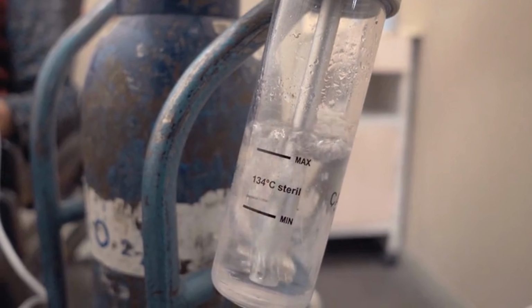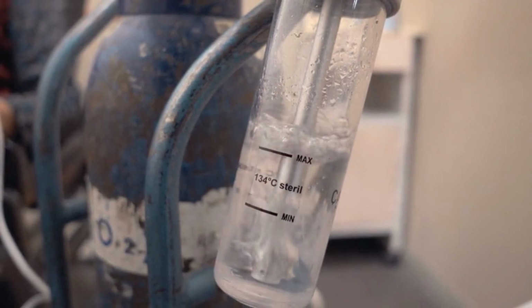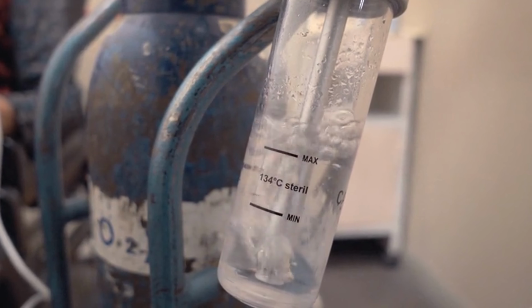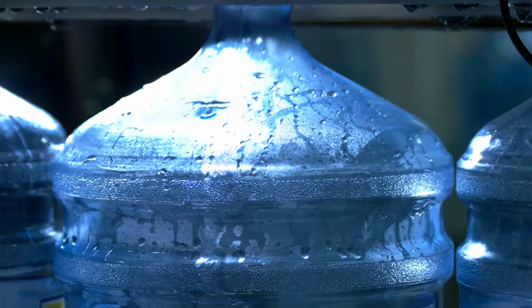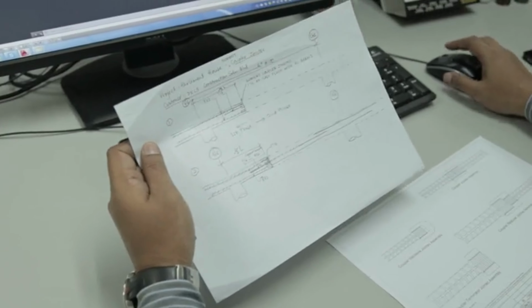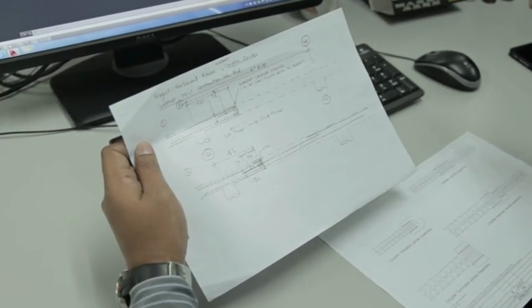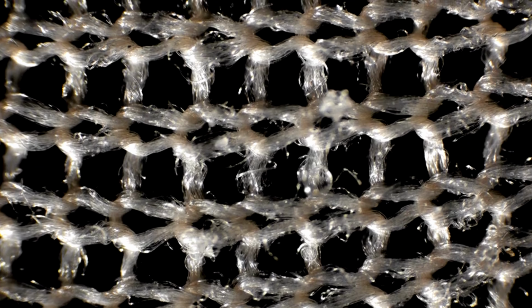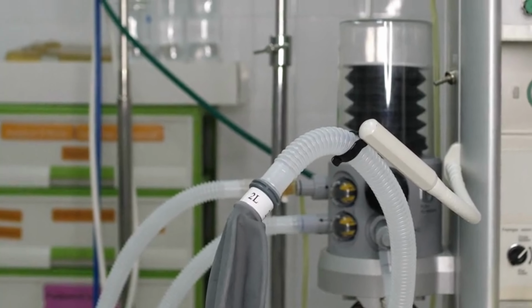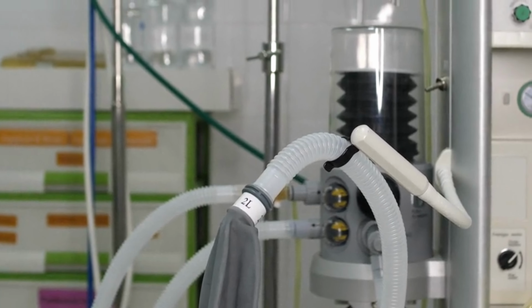5. Paper formation. After pulping and refining, the pulp is diluted with water, typically 99% water and 1% fiber, and pumped onto the fourdrinier or cylinder machine to form the paper sheet. Key steps. Wire section, sheet formation. The diluted pulp is spread onto a moving wire, a mesh-forming fabric. Water drains through the mesh while fibers start bonding. Suction and shaking remove excess water and improve fiber alignment.